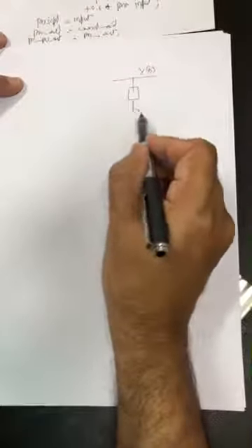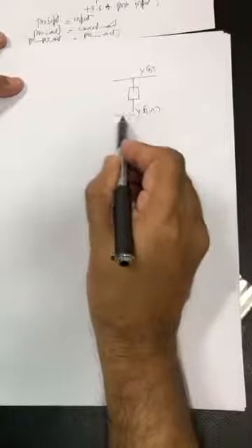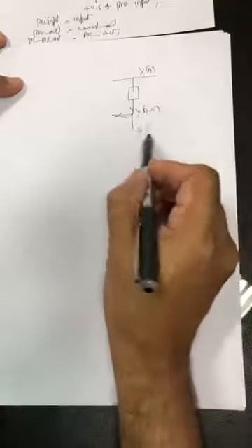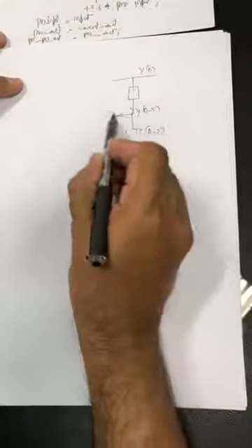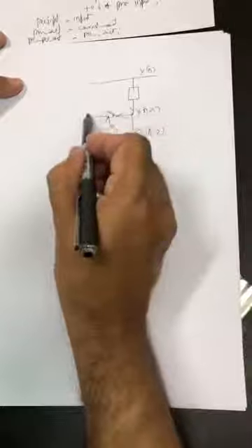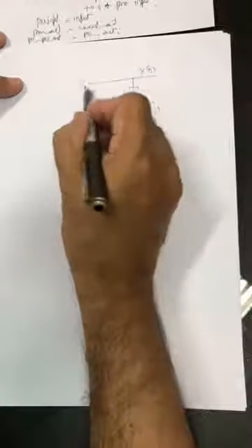So now if you try to make a flow diagram, which Dr. Ali has been making for you, and I perhaps need not repeat it, but I know Dr. Ali has shown you this: this is y of n which you intend to compute, this is y of n minus 1, and this is y of n minus 2 here, and here you multiply it with a1, and here you multiply it with minus a2, and then you add and add.